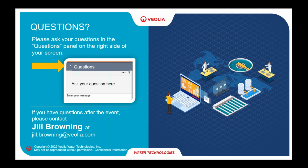Miriam? Yes, the main difference is when you're working with a biological removal of selenium, the reducing conditions within the reactor need to be very well controlled. The ORP needs to be very low. When we're working with the tracer SC, the conditions are similar to what we are seeing with denitrification.